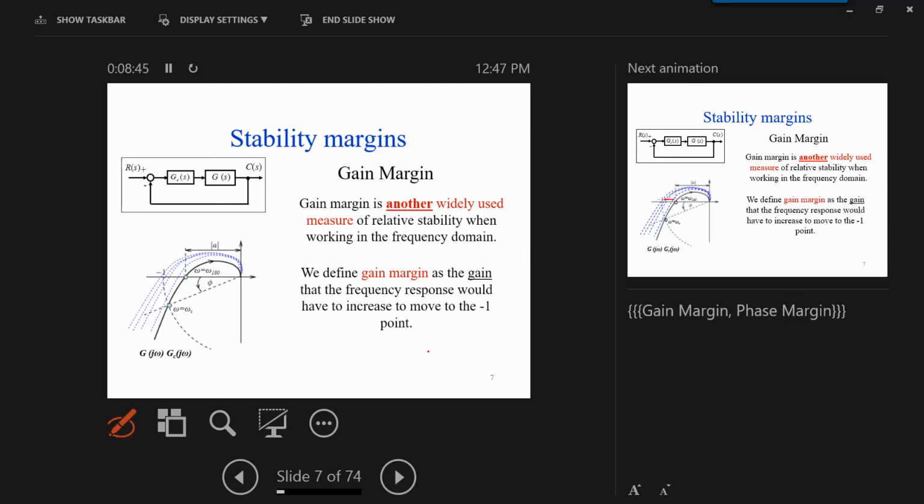This is how the Nyquist plot will look. At high frequency, the system magnitude goes to 0, and this is why, with the increase of frequency, the Nyquist plot goes to 0. Now here, this is interesting: the crossing of the negative real axis. Why?